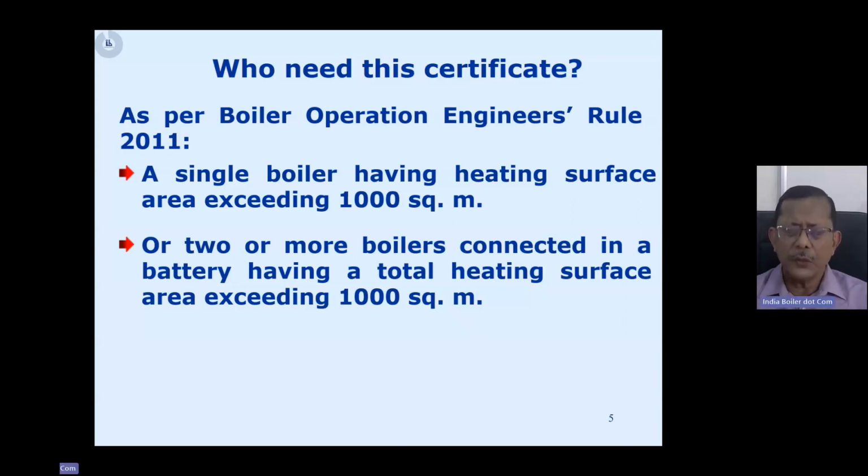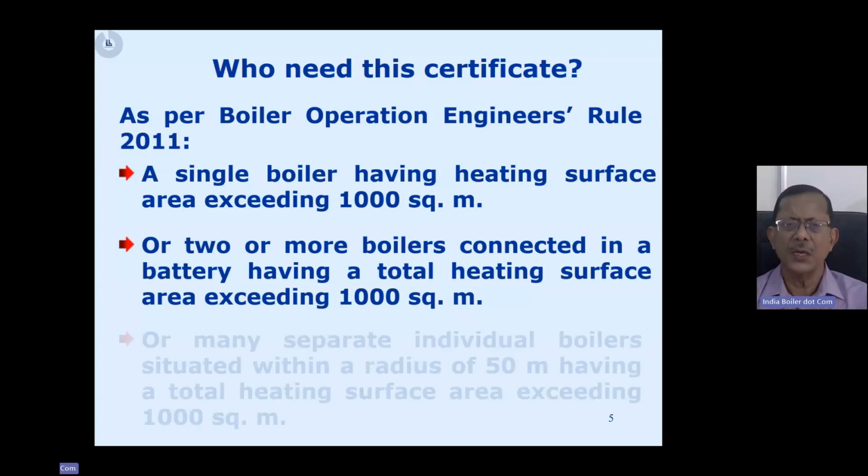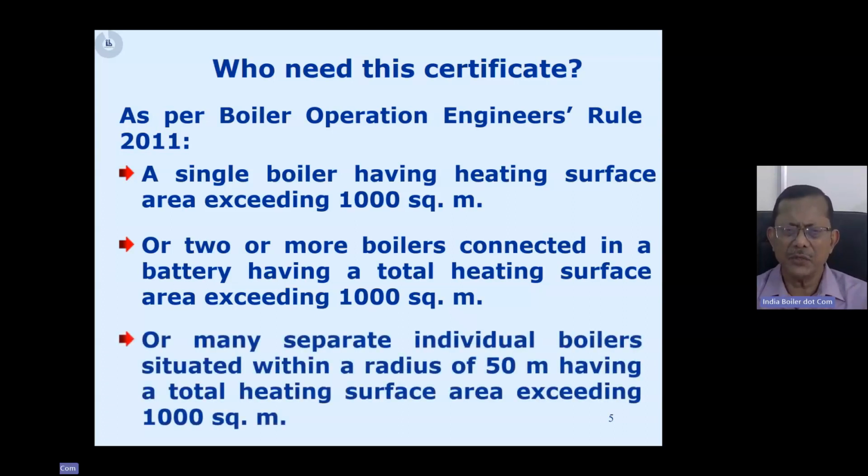Or if you do not have boilers in battery, but individual boilers, so say many separate individual boilers, but these are all situated within a radius of 50 meter, and the total heating surface area is exceeding 1,000 square meter, then again you require a BOE certified engineer to take charge of that boiler system.